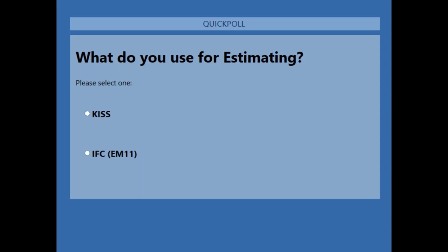Can you have an option to add in quantity for studs? This is not an option right now. They wanted to put in the quantity for studs and then the minimum distance on the left and right end. We don't have that right now, but I did turn this in as well to the development team. We like to have the first stud and the last stud shown for shortening reasons. Plus it looks a lot better on the detail anyway. Obviously in the model you have them all, but in the detail you just have the first and last stud with the total quantity.